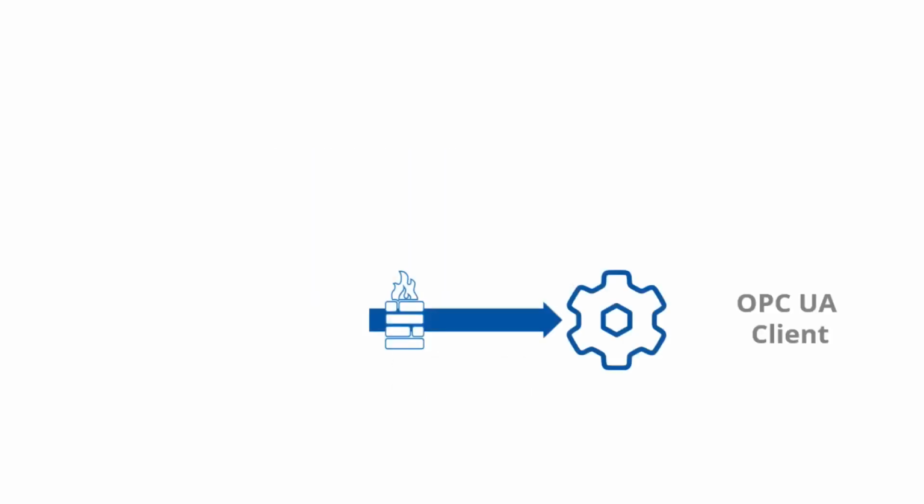When the connection is initiated, when it first starts, you want to override the OPC client values with the slave's values, the OPC server data. So choose the Override option. When the connection is lost, you want to mark the data quality for all points over there on the master as Not Connected. So choose that option. You can ignore the rest of the options for now. Click OK and Apply. Now switch back to the OPC client computer.